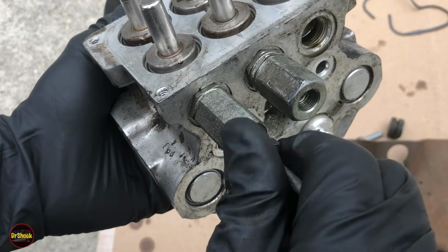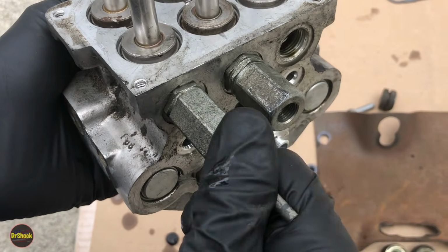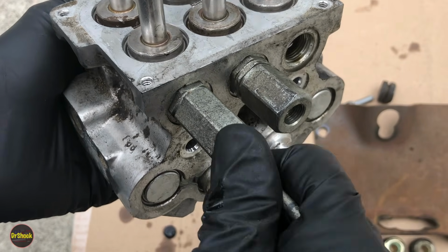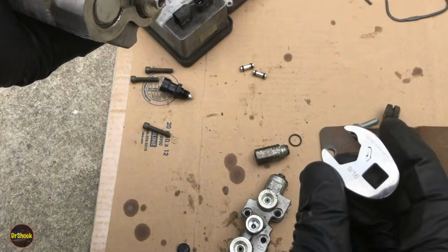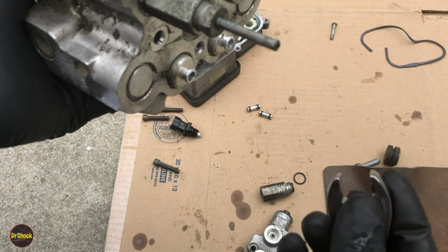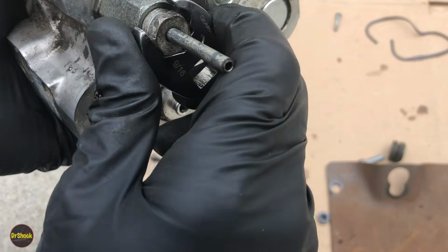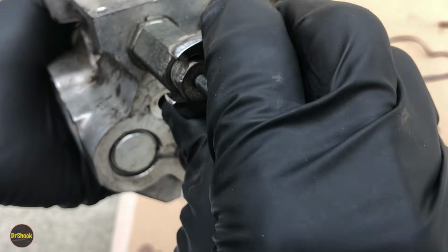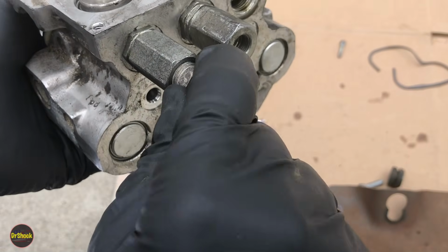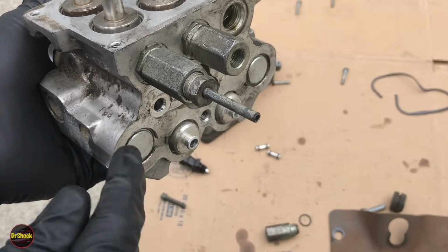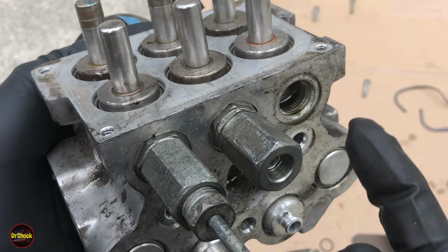So be sure that when you do this, what I like to do is tighten it down, loosen it, tighten it down, loosen it, and then on the third or fourth time of tightening it down, grab yourself a crowfoot that's designed as a line wrench type or a flare nut type, and you can use that to actually do your torque. This particular one is ratcheting, but anything will do. Then you can do the torquing of this, which is torqued to 22 foot-pounds, and then you won't have those kind of leaks. And if you happen to take this off to reseal it with the new O-ring, it's 23 foot-pounds on these connecting tubes.